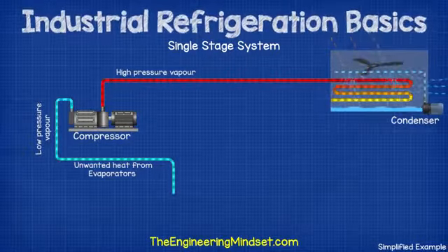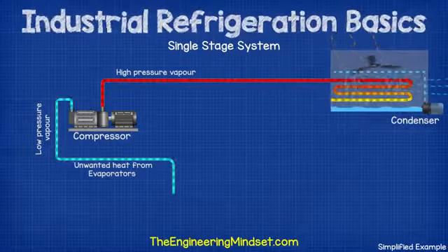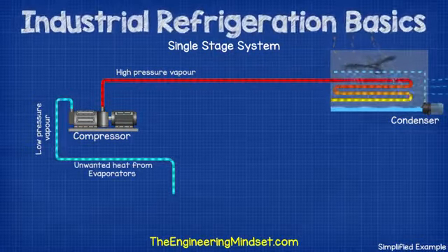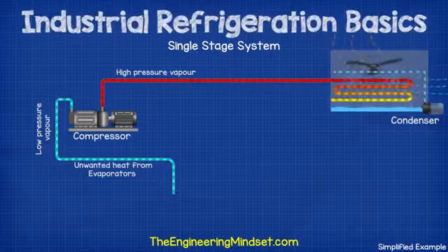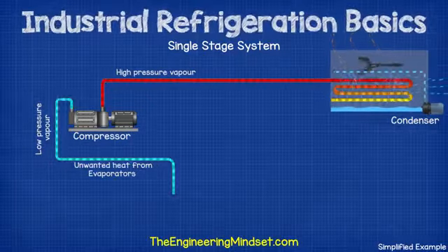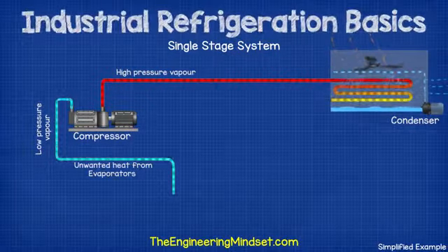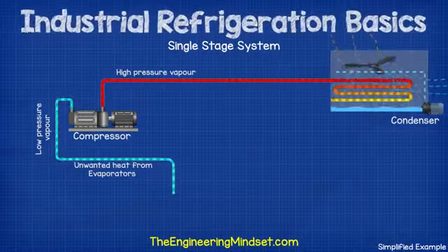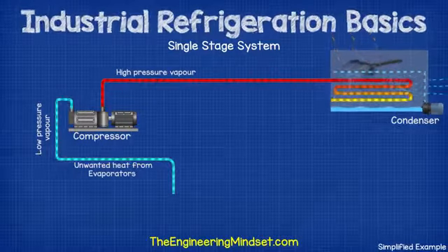Additionally, we'll often find a small pump spraying water over the pipes. Some of this will evaporate and help carry more heat away. The refrigerant is sealed inside the pipe and does not come into contact with the air or water. It is always separated, the two never meet or mix. Only the heat of the refrigerant passes through the pipe wall and is carried away by the air and water.